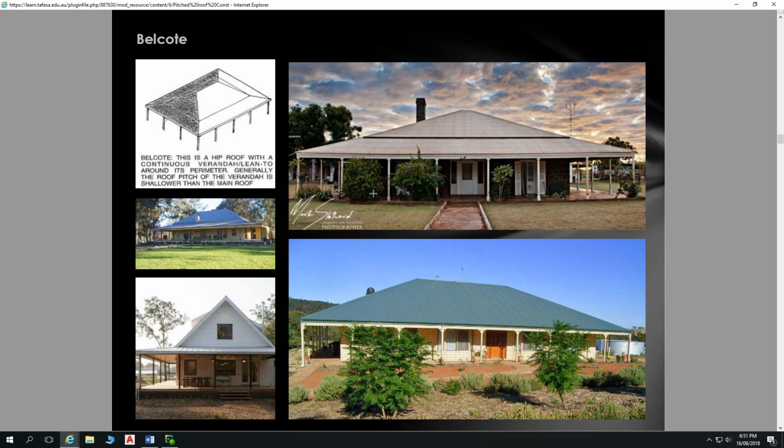However, with this example here, bottom right hand side, I think that tells us why we don't carry that pitch. It's great to have a steep pitch over the main house, but when we carry exactly that same pitch all the way down, we end up having our veranda beams sitting very low and obstructing our view out the window. It gives a real enclosed feel to the dwelling.